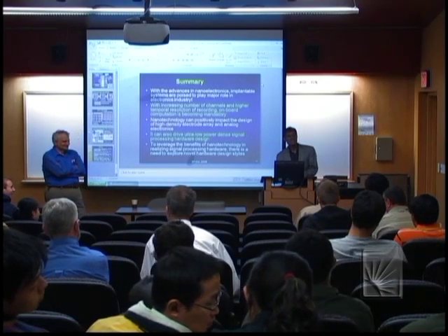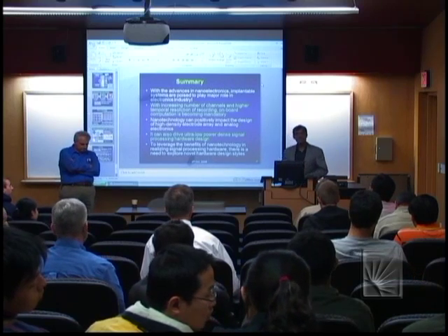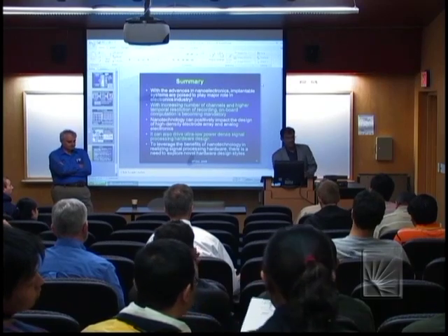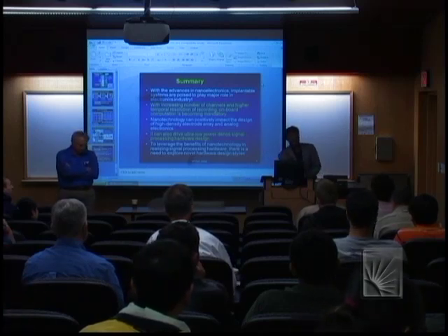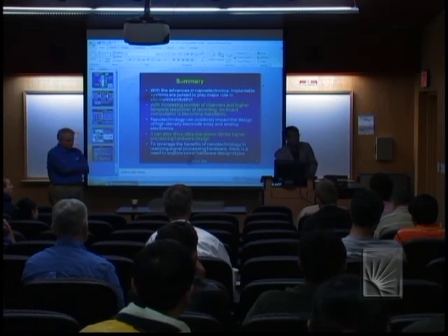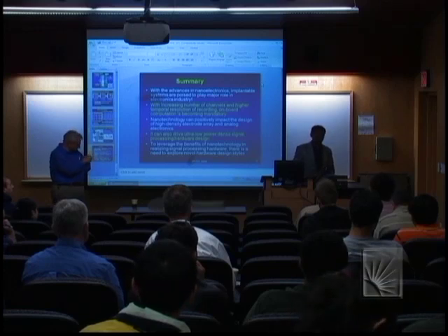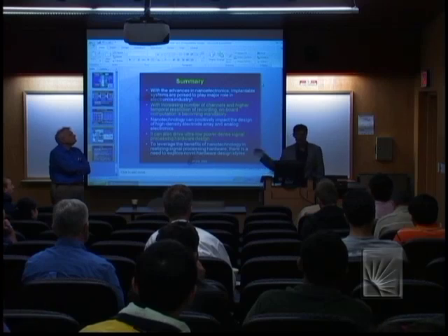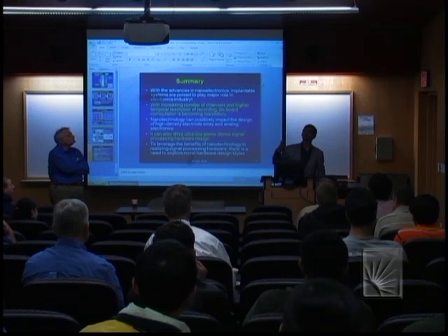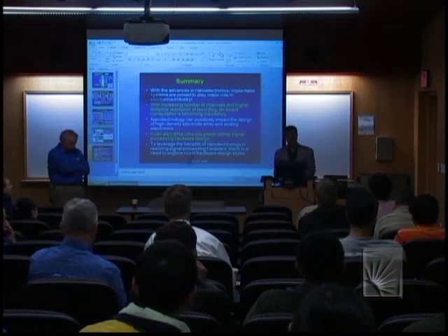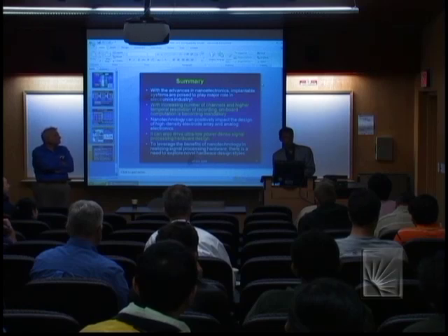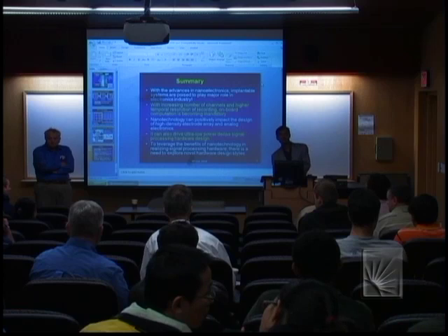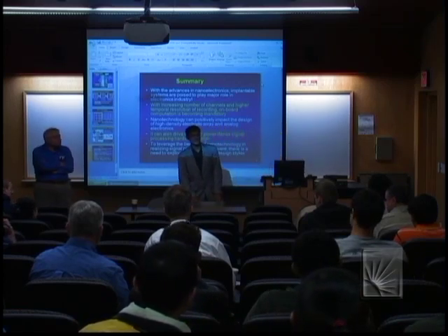For digital, of course, I can definitely say that nanoscale devices have huge potential. The reason is that we tried to implement this particular algorithm with 180 nanometer, and the die area we are coming up with is huge. You cannot afford that. How big are those dies? It was 2 millimeter by 2 millimeter for a very simplistic implementation. And if you want to afford higher channel counts, then the area goes up significantly. So in terms of area requirement, there's a huge benefit. In terms of switching power, there's a huge benefit, but definitely we have to take care of the leakage issue. So I personally believe that it has a strong positive impact on implantable electronics in terms of signal processing.